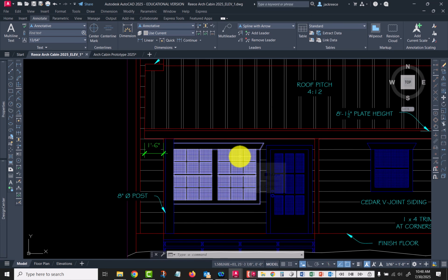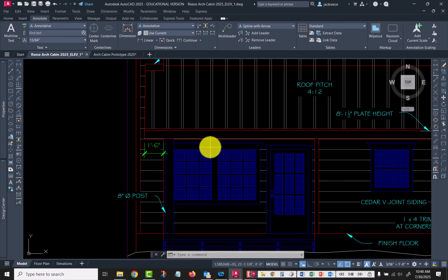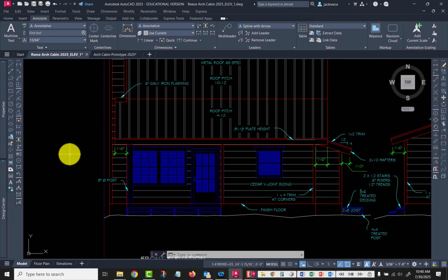Okay. Same way over here. Here you've got two windows that come in place, but they're shown as a single window unit. So go ahead and put both of them in based on their center lines from the floor plan, and then explode them and trim out the lines that you don't need, and then bring it back into a group. That is the best way to deal with that and fix it. I think that covers a lot of it.